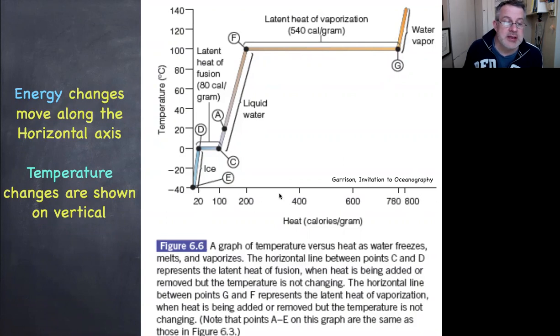So, in stages. And you can't jump one of these stages very easily. You can very briefly supercool or superheat across one of these phase transitions, but you can't usually go very far. So as you go back and forth in energy, you have to handle both the latent heating and also the sensible heating. Sensible heating is the heat that can be sensed by temperature.